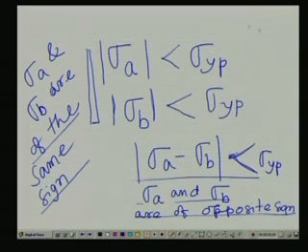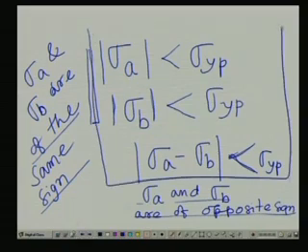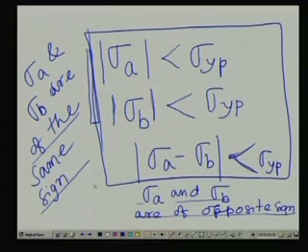So, these are the situations being expressed. Ultimately, what we get is the maximum shear stress theory as outlined here. That means, how do you design it? Once you find this particular stress at this level, this stress should be less than this one.